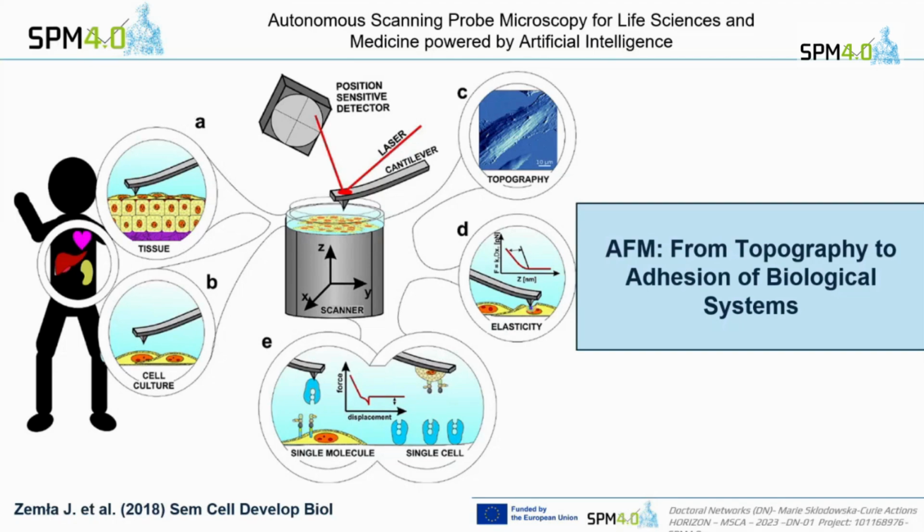In a rheometer, you can also have a second geometry, where you have a cone plate over the parallel plate, and here you cannot control the gap. The gap is controlled by the angle of the cone. But in plane plate geometry, you have a gradient of deformation, so the largest deformations are at the edge of the plate. If you have a cone plate geometry, then this is compensated, so you have the same deformation all over the sample.